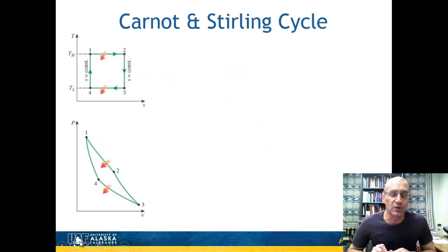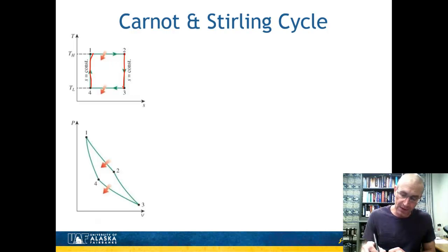Now there are a couple cycles though that are completely reversible, both internally and externally. One we saw before, which is the Carnot cycle, which has these 4 steps. This shows the Carnot cycle on a TS diagram. We have 2 isentropic steps and then 2 isothermal steps. We have energy coming from some value TH, we have energy going to some value TL, but it's occurring while keeping the temperature constant. And so in theory, there could be no temperature gradient.